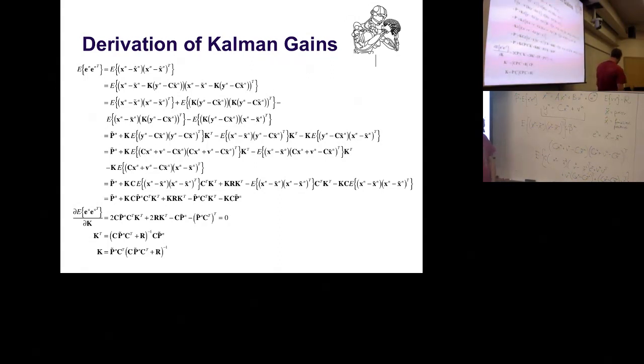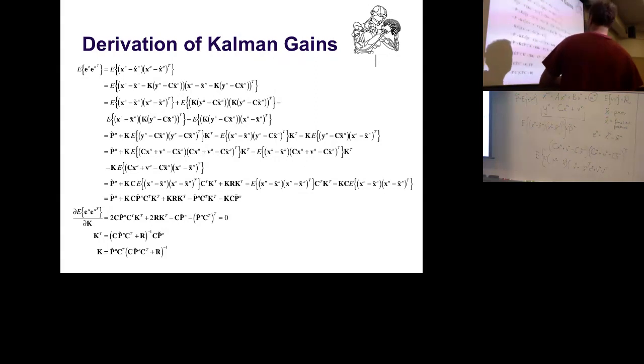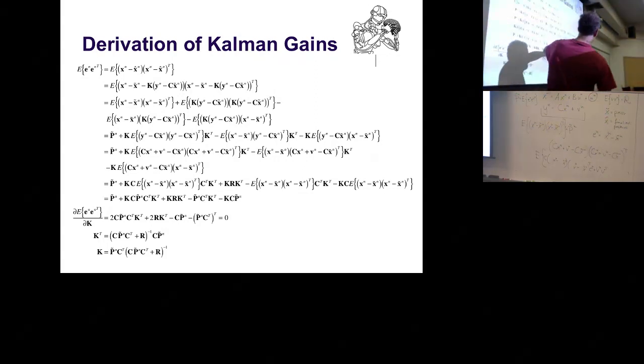And those terms are useful. Since Vn is a noise term, it is guaranteed uncorrelated with anything in there. And in general, if you have the expectation of uncorrelated terms multiplied, it becomes 0. That means these terms here actually disappear to 0. Very happy. And that's what simplifies those equations, so that I have only this term left and this term left. These cross terms went to hell, and I'm very happy.